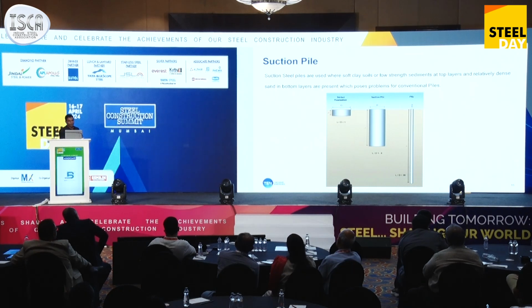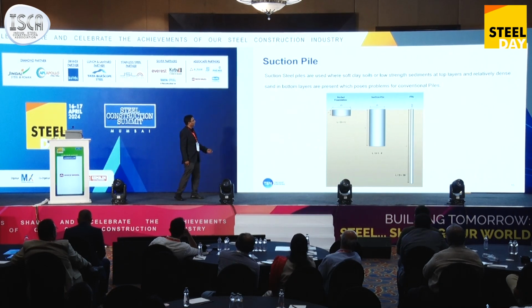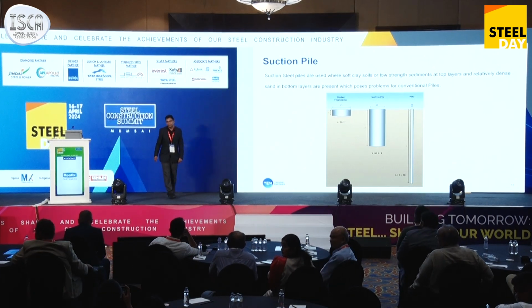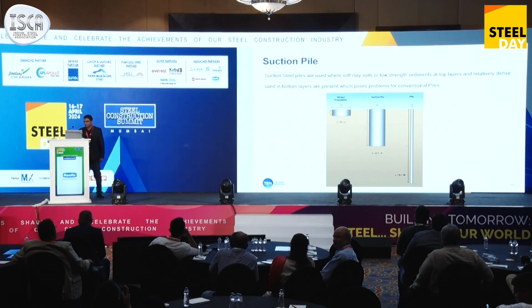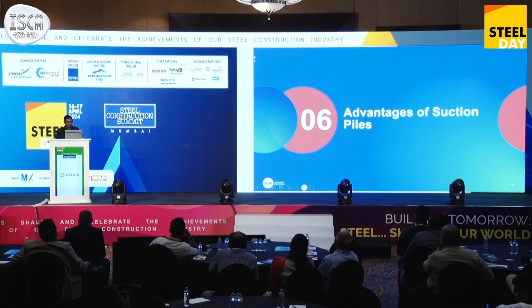Now as a thumb rule, if you see the penetration versus the diameter, if you go with a conventional pile, it is greater than 30 meter. That is the leftmost point. And if you use the suction pile, it is between 1 to 8 penetration to the diameter of the pile. And there are skirted foundations. These are for temporary foundation for installation purpose. There is a small video.